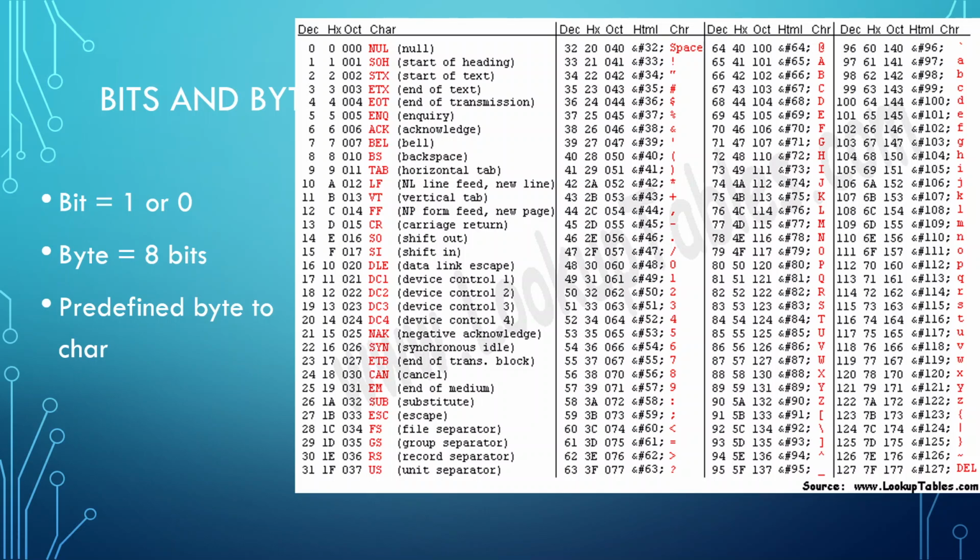You guys ever have to start dealing with serial? I'm gonna hit enter, and it doesn't send the actual enter command, but I want to send it enter. But you have to tell it either a new line or carriage return, or those two things. And depending on the hardware you're talking to, that's going to matter whether you send new line or carriage return. So it starts to get really kind of annoying when you are dealing with this type of thing. So just something to be aware of.